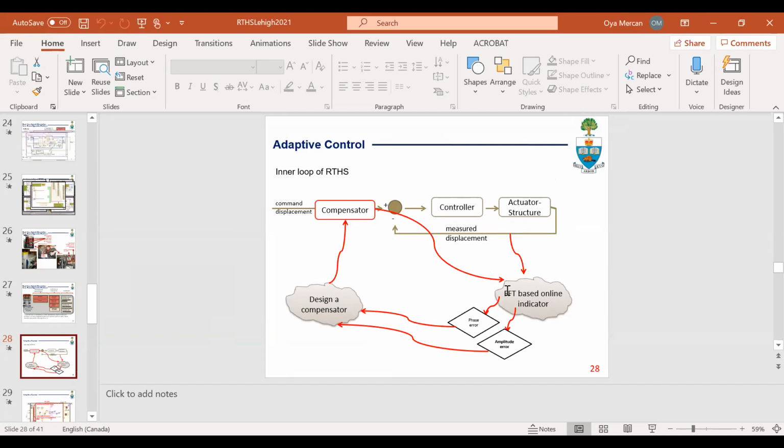because I didn't have a chance to go into the details, but in order to implement this, you have to have a moving window. And the first time you start actually taking an action is at least you should have half a period long signal. Once you have that, you can accurately calculate the errors and design your compensator.